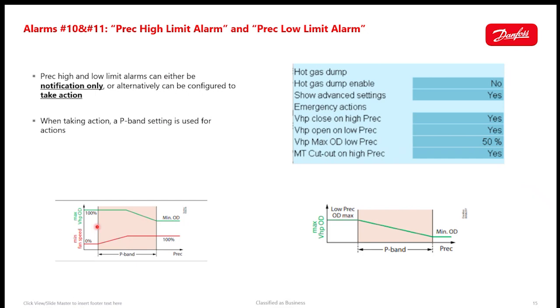And so if you're seeing maybe the high pressure valve is closing off too soon in your mind, or gas cooler fans are running more than you want them to, one possibility here is just that the P band is too large, or maybe your P-rec max is too low, and you might need to consider raising those values a little higher to make that adjustment, and maybe to allow that receiver pressure just to float up a little bit more. Not that we're looking to risk any relief valve issues, but there's some potential there that that receiver pressure can be allowed to get a little bit higher before some of these actions are taking, knowing that those actions start before we actually reach the P band limit.